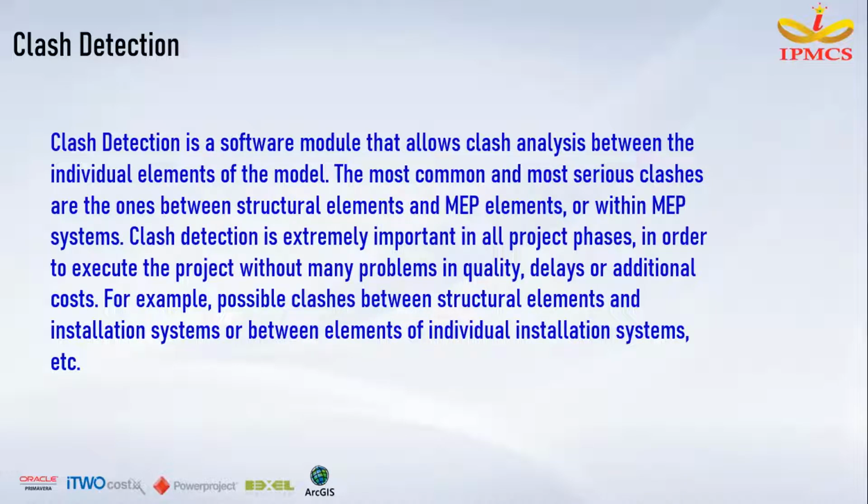Clash detection is extremely important in all project phases in order to execute the project without many problems in terms of quality, delays or additional cost. Say for example, possible clashes between the structural elements and the installation systems, or between elements of individual installation systems, etc.